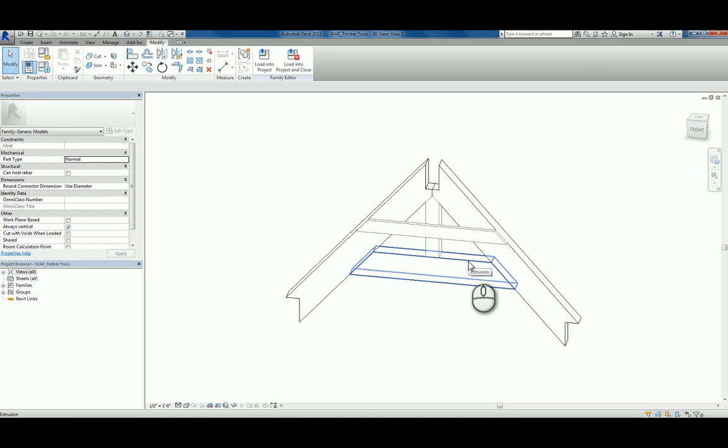So when you're using an instance parameter, it's only going to have the checkbox in the properties to turn it on and off. So this family right now is not set up to have that capability of being able to set the type and find the cost per type of that. Does that make sense? So that's when I say you have to take into consideration the model elements and how they're generated to be able to do a lot of this stuff.